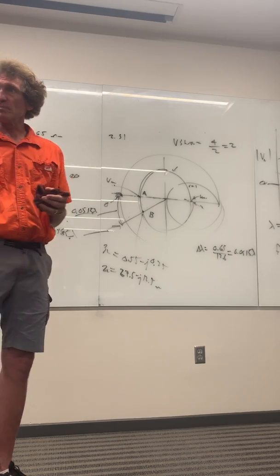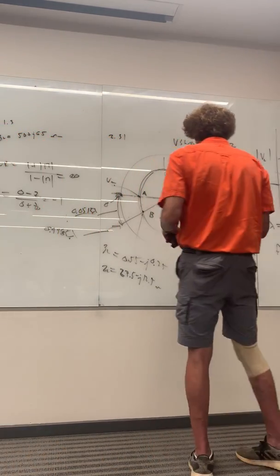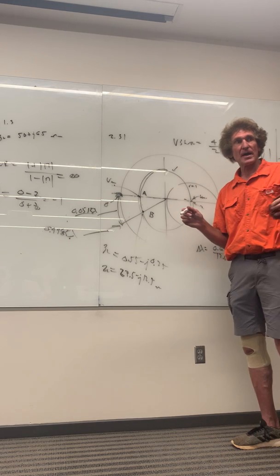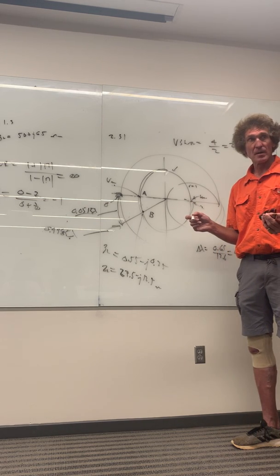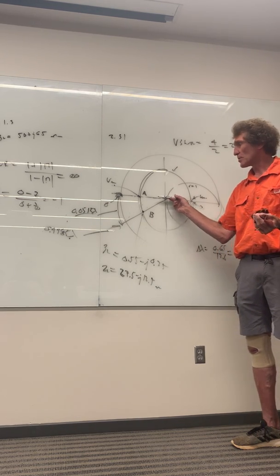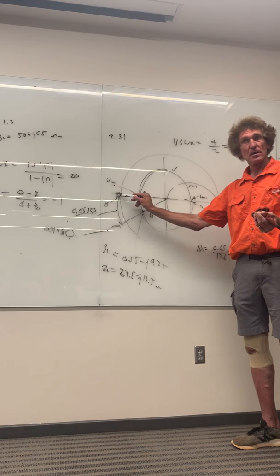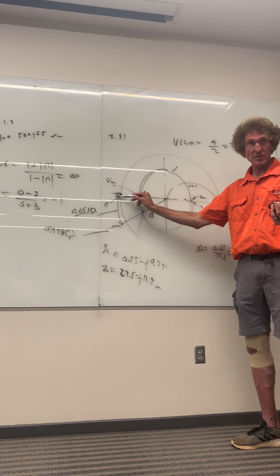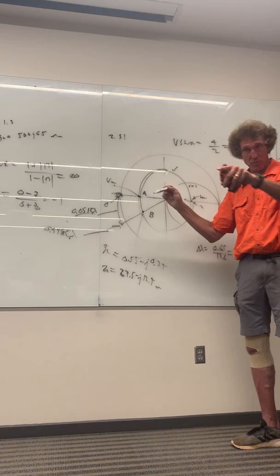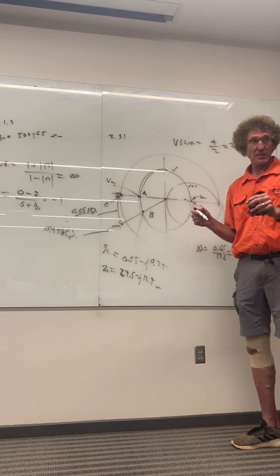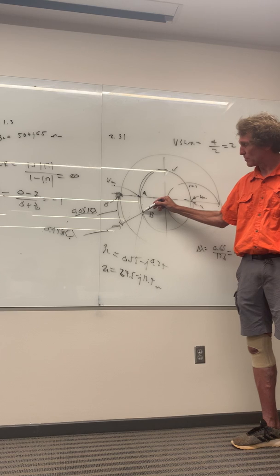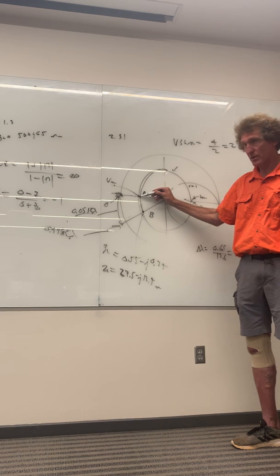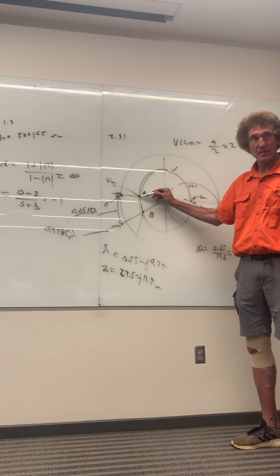The whole idea is this: the minute you have the VSWR, you have the radius of that circle. After that, if you put a short circuit in, we know the short circuit is going to occur right here, right? So at that point, we locate the load right there. Then from there, as we move from the load point towards the generator, we hit the V min, right? So here's the low point. As we're moving wavelengths towards generator, we go through that point, wouldn't we, class? Are you following me on this one, guys?